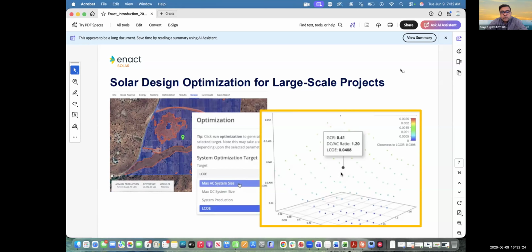Excellent. I would like to add that if you're looking for an optimized solar layout, for example, selection of the lowest cost of energy, playing with GCR or DC/AC ratio, you can get to that here. It takes a few minutes to run all the scenarios and gives you the optimum, and then you export that final run into PVCAD for AutoCAD. So you eliminate a lot of time wasted later on if you get to the optimal design and then go into PVCAD, of course, for the rest of the layout details, generation, and yield, as well as the SLDs.